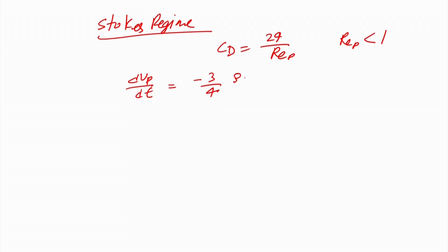From there I am starting again rho f upon rho p, we have already derived this. So, I am writing this equation directly into Vp square upon dp into Cd. Okay. So, this is Fd and m dV upon dt was there, m I have converted in terms of rho f into pi by 6 dp cube. This we have written in terms of pi by 4, area we have written in terms of pi by 4 d square. So, from there we are doing it. Now, Cd value I can put as 24 by Re.